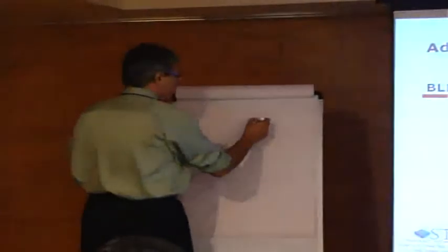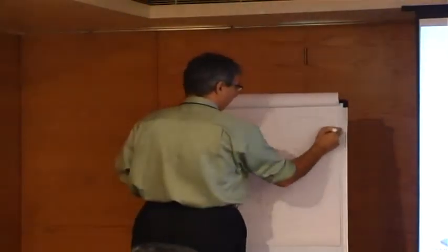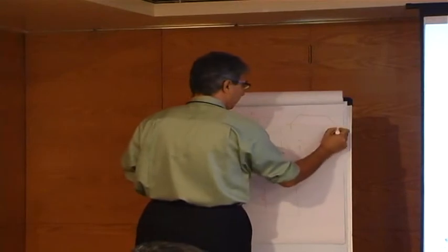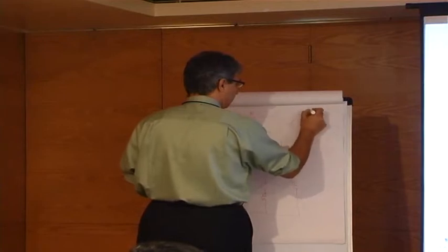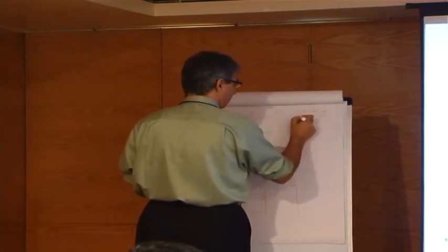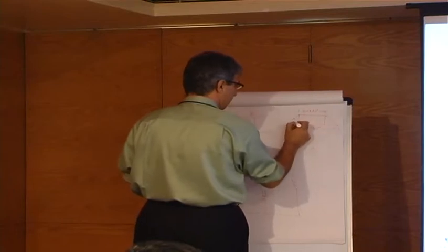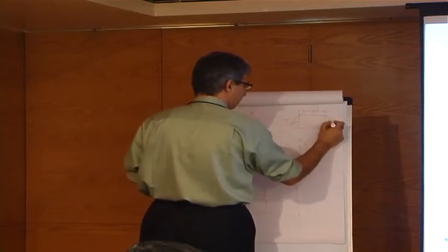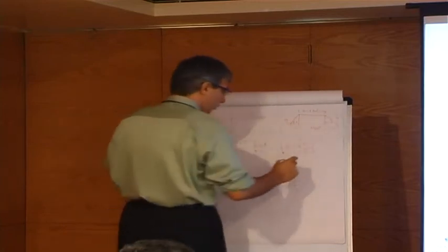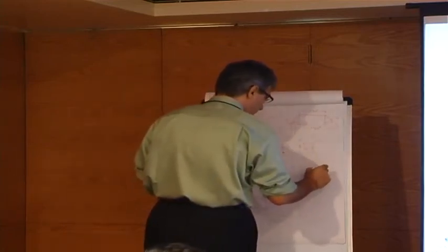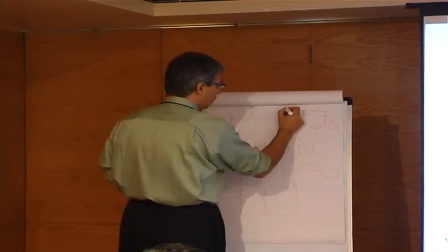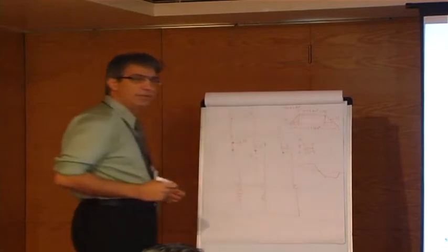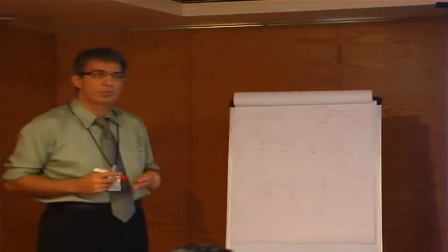So this is your back EMF signal, and this is actually 180 degrees, and this part here is 120 degrees. So this and this becomes essentially 30 and 30. The back EMF voltage, this is what we're trying to simulate. So this delay 1 is your 30-degree delay. Then the rest are computed accordingly.